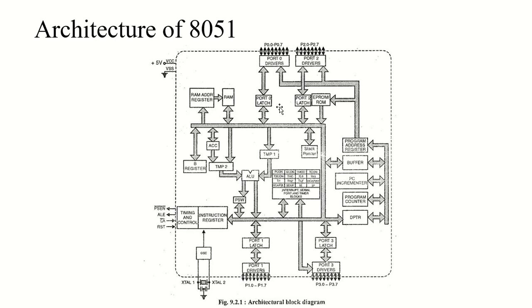Now the SBUF register comprises two registers physically. One of them is write only, and is used to hold the data that is to be transmitted out from the microcontroller, while the other is read only and holds the data that is received from the external source via the RxD pin, right?